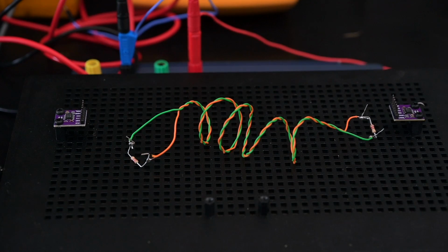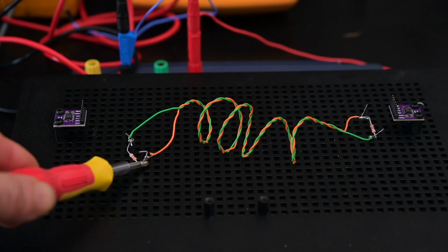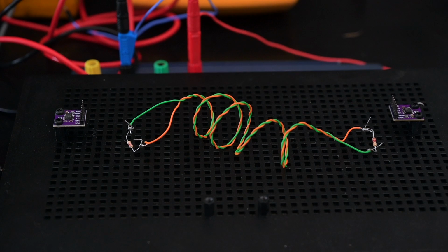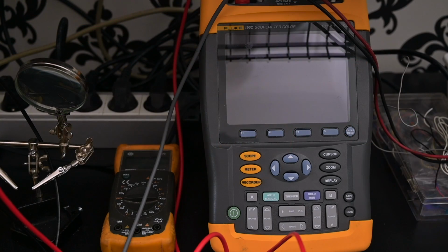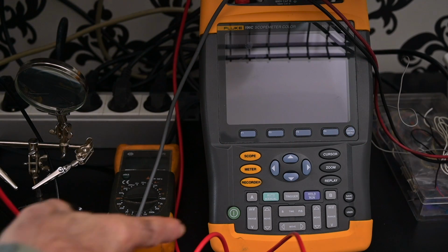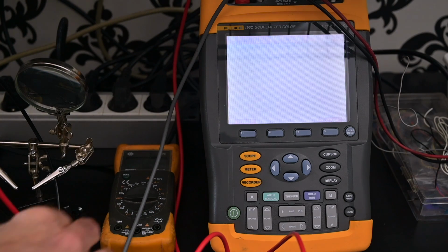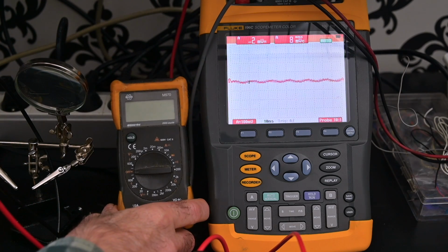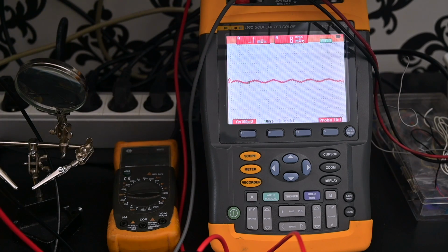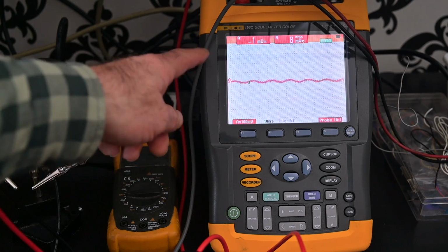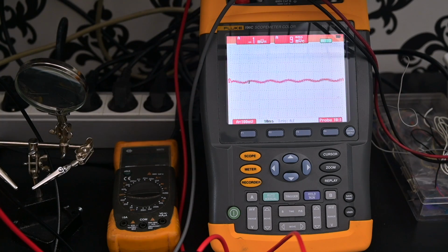So here we have the breadboard. We have one transceiver on one side, and another transceiver on the other side, and we're going to connect those up with our twisted pair cable, which is actually our CAN bus, with the terminating resistors both on the left and on the right. For testing the electrical signals, we will be using an oscilloscope. A voltmeter might work, but it's not all that easy to demonstrate. And we'll use the different traces on the oscilloscope to show all the different signals.